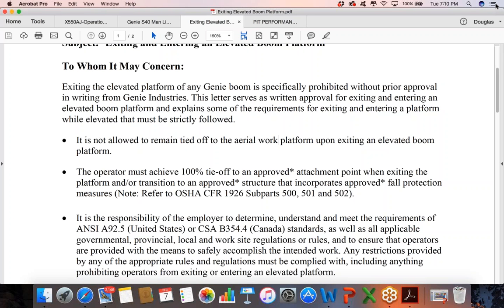All right. So what are we looking at? 1926.1100, we're looking at a wide range of conditions that can fall under the classifications of a job site hazard. So we're going to talk about a few hazards. Poor housekeeping, of course, could cause slip, trip, and fall hazards. Could cause fire hazards. Could hide sharp edges. Could hide biological hazards, wildlife, plant life. Also, defective or unsafe tools or equipment, equipment that we haven't pulled out of service.